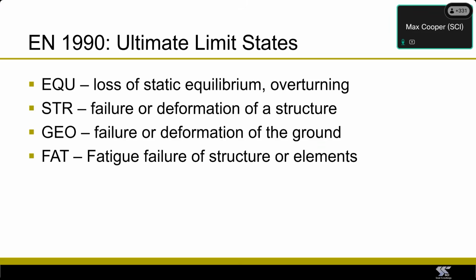So looking at different ultimate limit states, in EN 1990, we have 4 different categories. We have EQU, which represents the consideration of equilibrium, and I would suggest that this is fairly uncommon for most common structures. This is something you'd be looking at if you're worried about overturning or sliding. We have the STR combinations, structural failure. This is what we use hopefully every day.